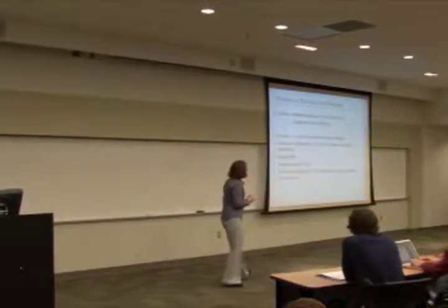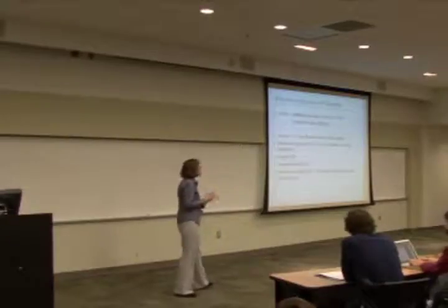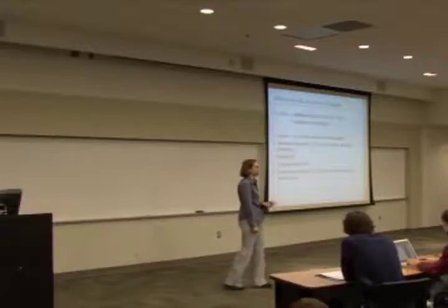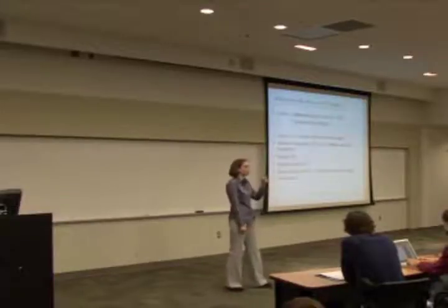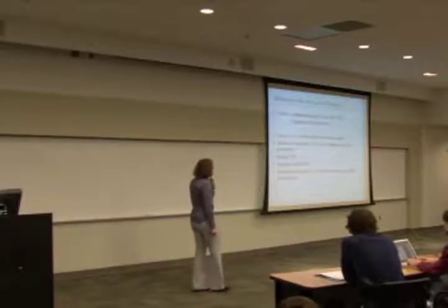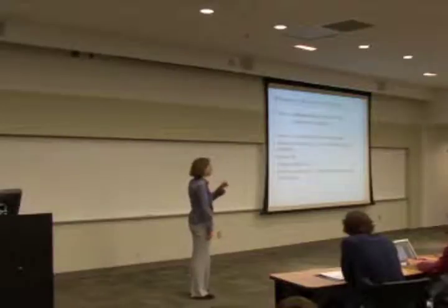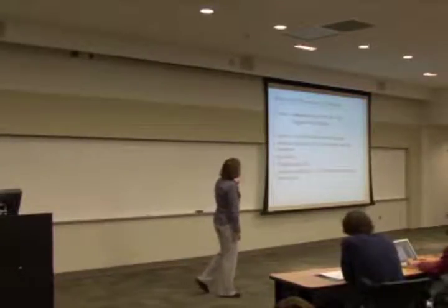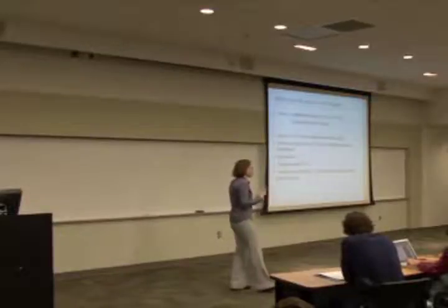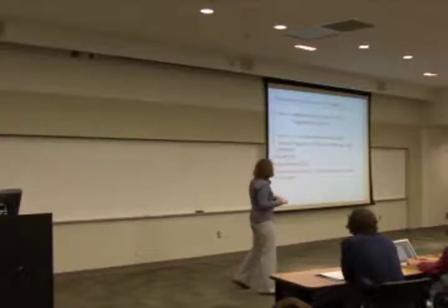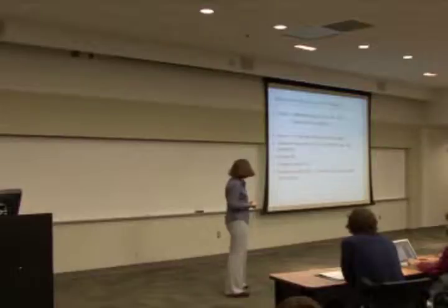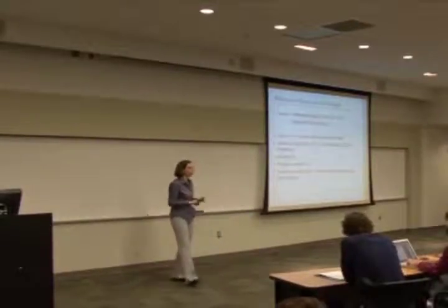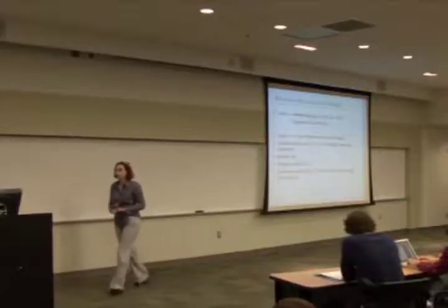Yeah, they are there. So we definitely need a program counter to tell us where our program is at. We need the memory to tell us what is stored at the address where the program counter is pointing. We need register files to make communication between the arithmetic logic unit and memory a little bit faster. And we need an instruction register, and that's the new element, and I'll explain in a moment why we need that.